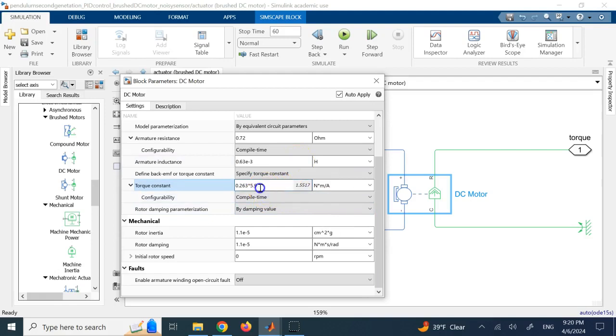So what I did, I multiplied that by the torque. So I'm artificially adding that gearbox ratio in this block. And if you want to include the efficiency, you can multiply that number here as well. Okay, so if it's 81%, you can multiply by 0.81, and this brings your effective torque a little bit down. But again, if you want to plug in efficiency, you can do that.